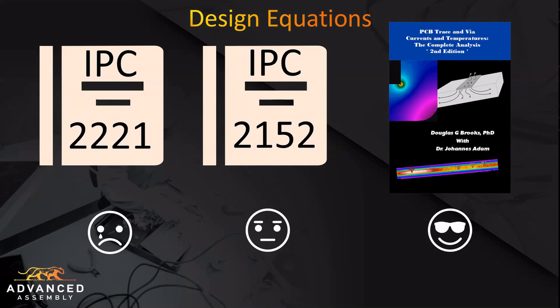So the equations from the IPC 2221 are derived from data that was formulated in 1956, actually, by a pair of pretty much unfunded researchers who really listed their results as tentative. The idea that an internal trace must be derated by 50% appears to come from an assumption in those charts, but not empirical evidence. It turns out, just through our research for this talk, it was really wildly inaccurate. And internal traces can actually be derated as little as 5% in many cases.